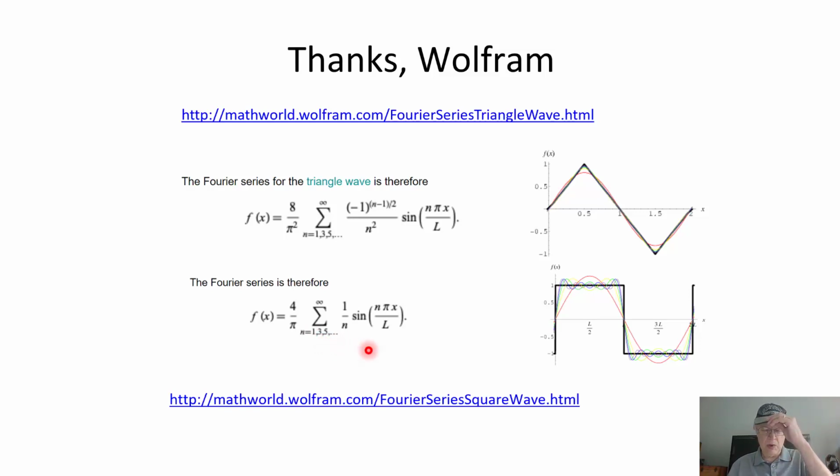Okay, and so you need, oh, I don't know, 5, 10 of those signals to get a reasonable approximation to the square wave. Now the reason that those high frequencies are required is because there's a sudden step up. If this is a time domain, then we're going along in time, my signal's low, and then boom, over a very short period of time, it jumps up, and then boom, it jumps down over a very short period of time. So because there's a short period of time involved, I need to have high frequencies present in my Fourier series to simulate this wave.